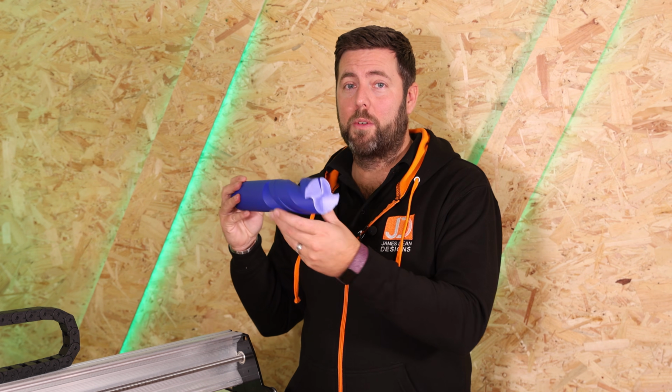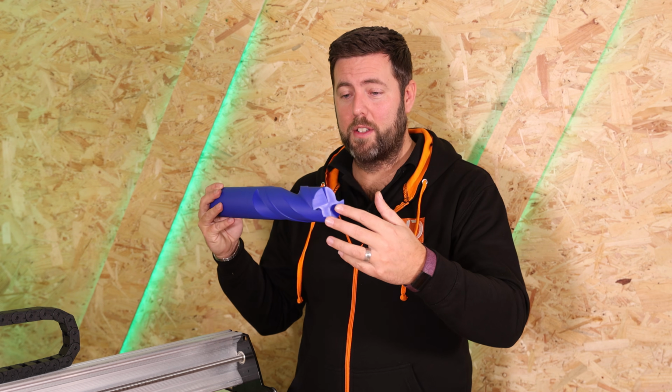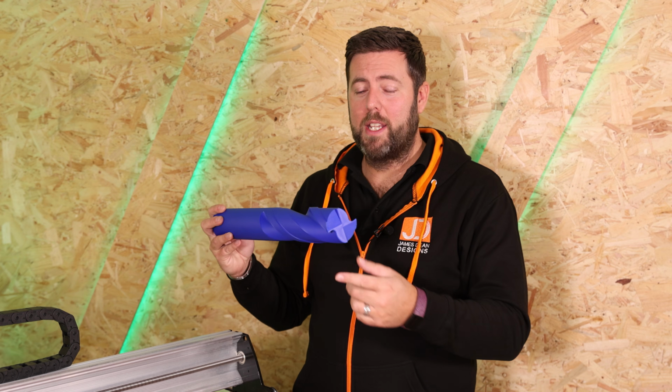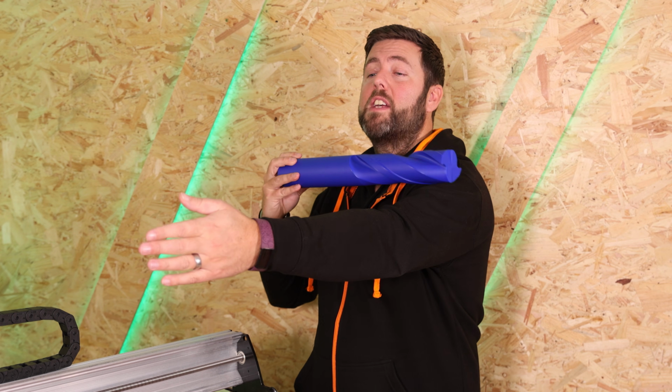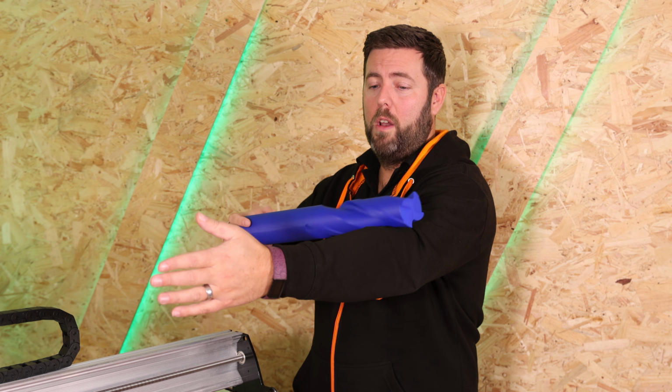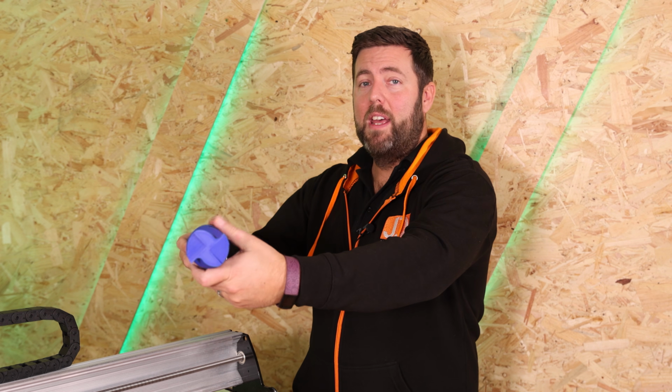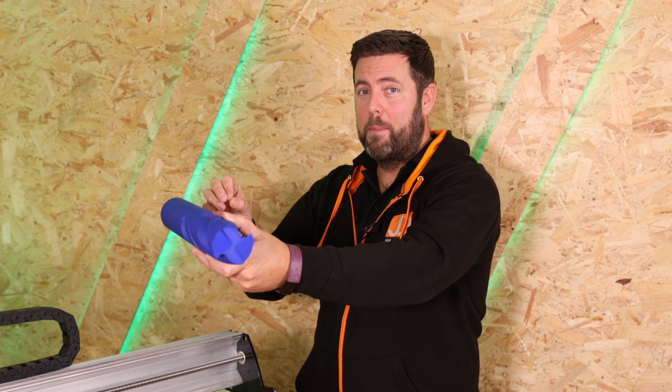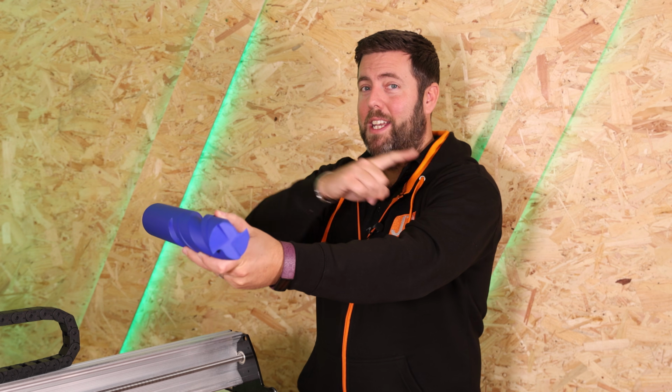Now, the way we achieve that figure is, well, I find it easy to think about your bit being horizontal instead of vertical. Obviously your spindle has an RPM, a revolutions per minute, and your bit also has a diameter or a circumference. Think about something simple like 3 RPM, 3 revolutions per minute. Imagine putting your bit on a flat surface and rolling it 3 times. We go 1, 2, 3. Now that speed that I referenced, or the surface feet per minute, is the distance from point A to point B. And ultimately that figure allows you to calculate what the bit is capable of cutting.